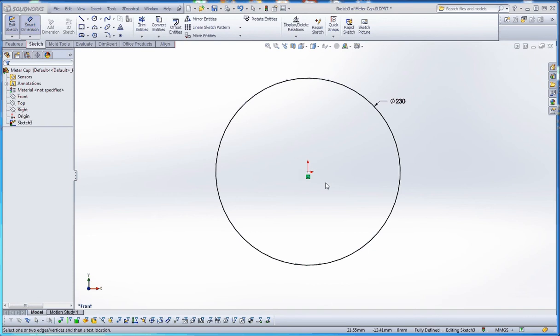So one thing I want to do with this is I want to sketch in all my geometry that's going to be associated with everything we're going to be doing with this meter. It's a good technique to put all your sketching elements, if you can, into a top sketch. Sometimes the top sketch will be associated with a feature. Sometimes it's just out there all by itself, and the features that follow below that refer to that sketch. It's just a quick and easy one-stop shopping sort of a bit of advice I can give you here that will help you model some very complex models. If you remember that coupler model that I showed you, it's got, I don't know, about 50 or 60 entries below that. I have a couple different sketches and sketch pictures I was using in order to model that, but we're going to save that for a future film or another film.